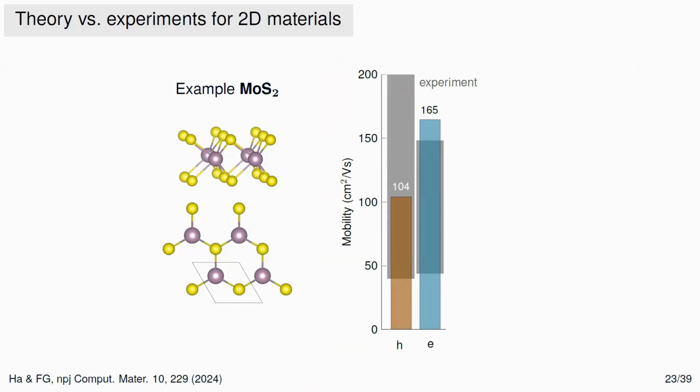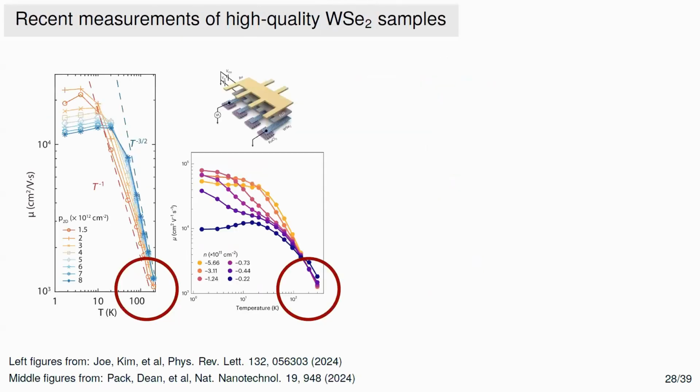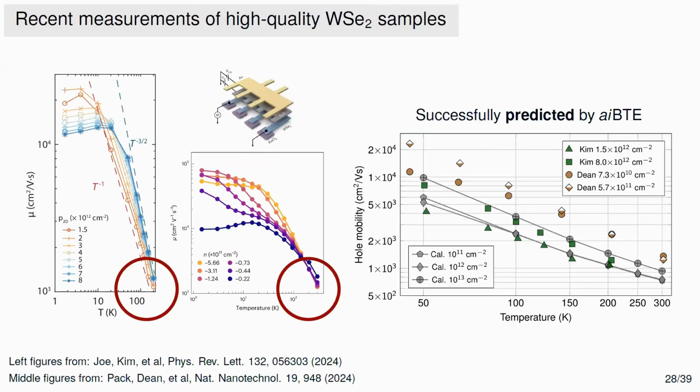I think, let's say one challenge with these materials specifically is that realizing p-type contacts is challenging because the work function is very high. So their claim is that with ruthenium trichloride, they managed to achieve good ohmic contacts, but others have not been reproducing that yet. So that's really a question of, is that the reason why it works so well, or is there something else? For now, at least their claim is that getting good p-type contacts was key, and getting low impurities. But I don't know more than that.